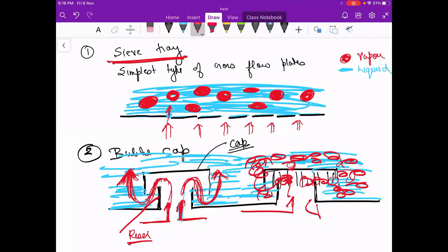But obviously the pressure drop will be high, because the gas is going upward, so there will be an obstruction in front of it. That is why the pressure drop will be more. If the pressure drop is more, then the flow rate will be reduced, so it means more time will be there, as compared to the sieve tray, like in the bubble cap.